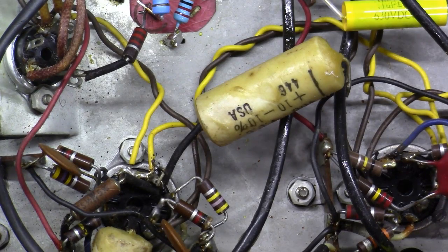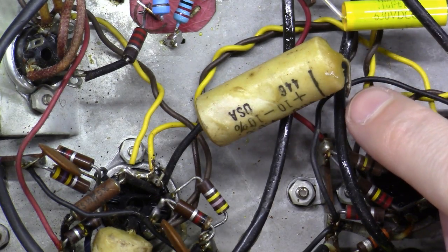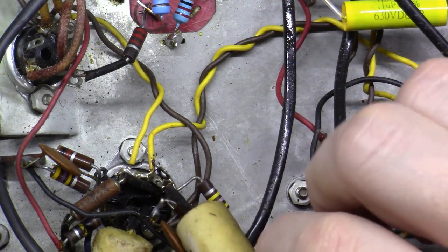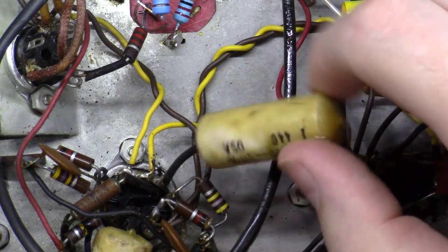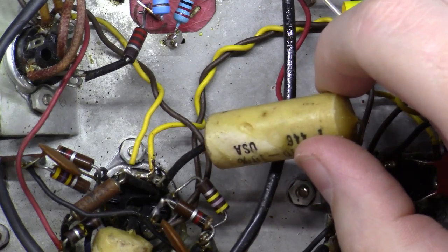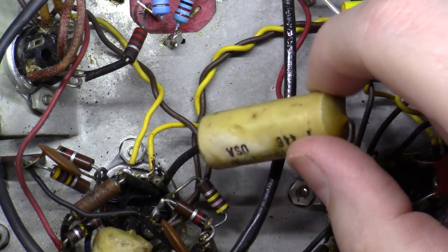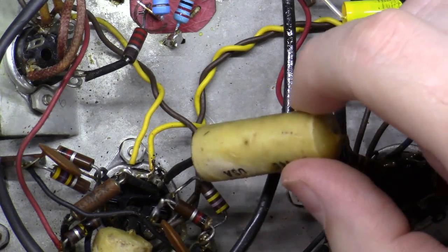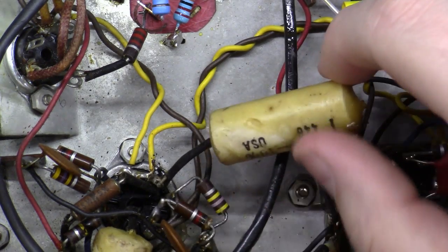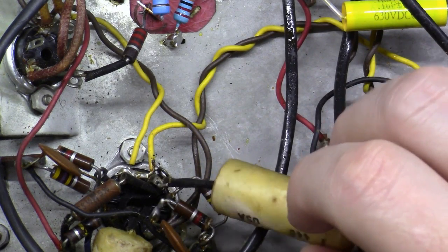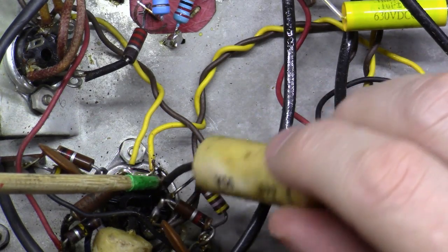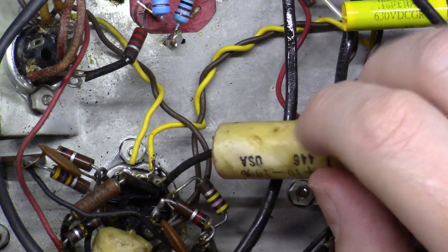Alright, something interesting here. This ICO was a kit that someone built way back in the day, and I want you to see this. I cut one side loose here of this coupling capacitor. It was connected over here, and I started bending it back out of the way to get to the other side, and look what I found. You can see down here at this pin socket, whoever built this originally never soldered the other end of this coupling capacitor. I'll call it factory error by the original builder here, but you can see I'm wiggling it like crazy, it was never soldered.